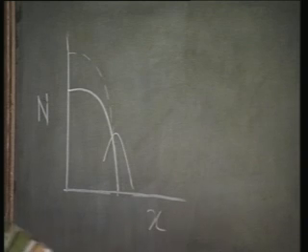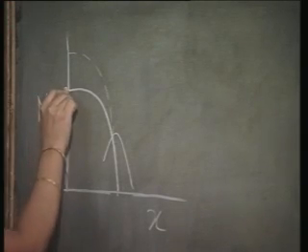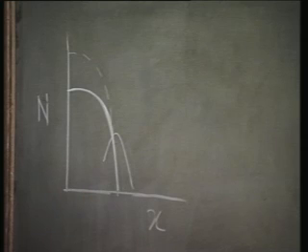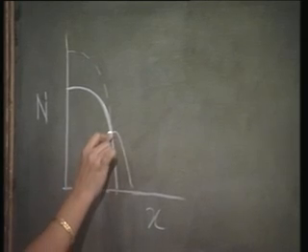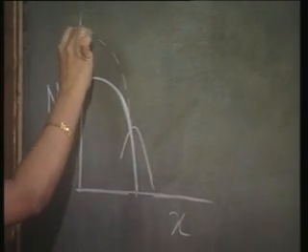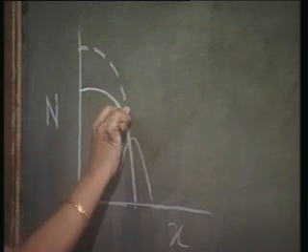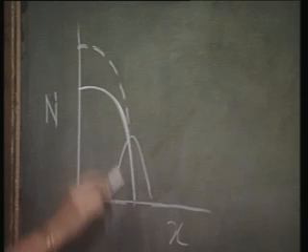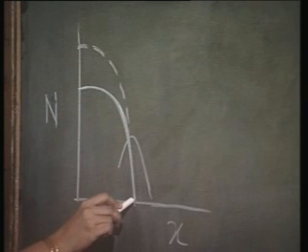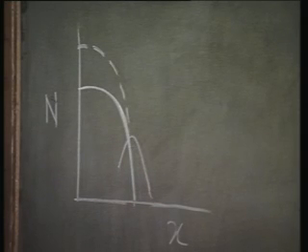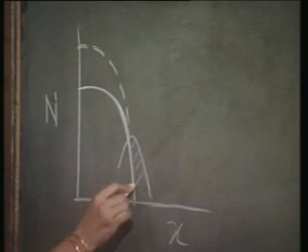That is to say, I use two implantations for the base. This is for the extrinsic base and this is for the active base. And this is my emitter implantation. I adjust the base implantation depth such that the extrinsic base implantation depth coincides with the emitter, and I have a second base implantation in order to obtain my active base. So, this is actually the active base.